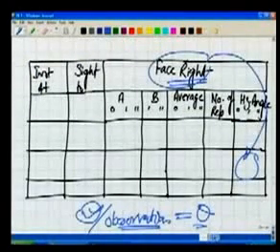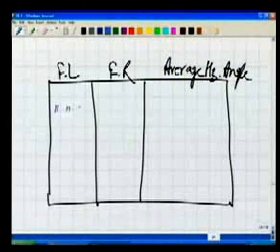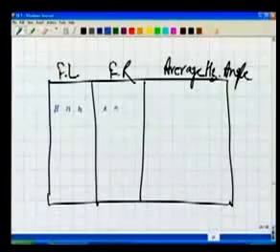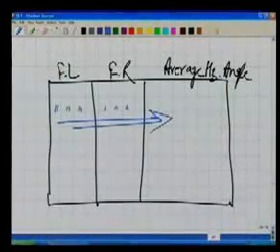So finally what we do, we have the angle for face left, face right, and we take the average of these two. We'll talk about this later on, why we need to take the average of face left and face right. So this is the method of repetition.